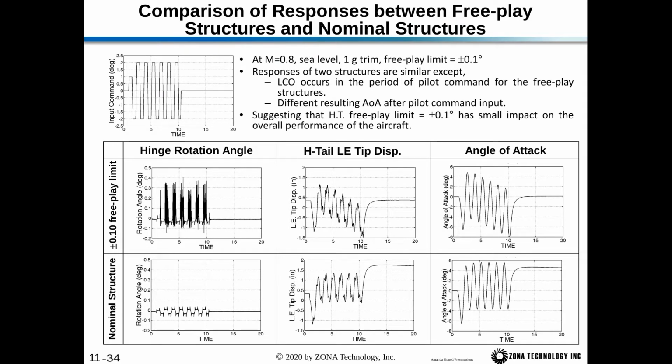Now we'll want to compare the responses between the Freeplay structures and the nominal structures. So at Mach 0.8, sea level 1G trim, Freeplay limit of plus or minus 0.1 degrees. The responses of the two structures are similar, except the LCO occurs in the period of the pilot command for the Freeplay structure, and we have a different resulting angle of attack after the pilot command input. So on the top, we have the Freeplay structure. On the bottom, we have the nominal structure.